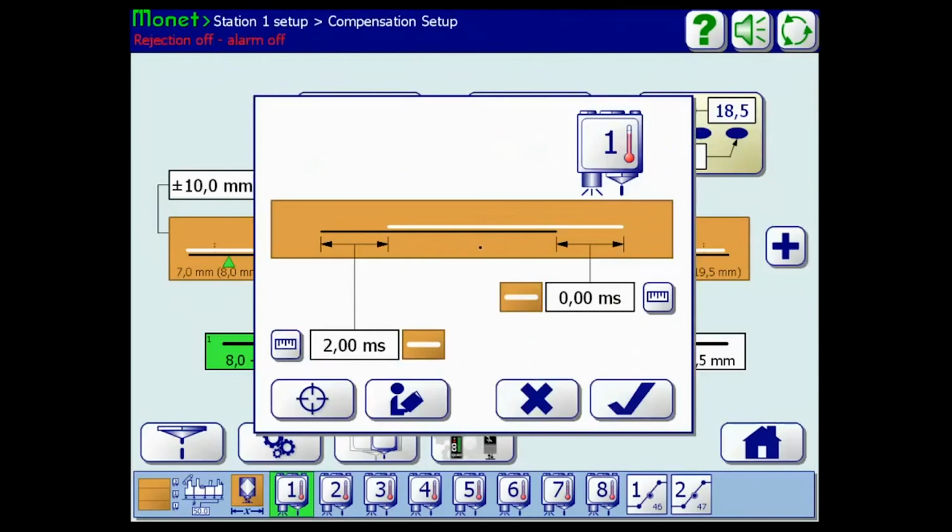There's on and off compensation for every glue applicator. This is just a generic image when you open up the menu. It's basically telling you that, in order for the glue to actually start where I programmed it to start, we have to compensate for the glue extruding from a nozzle and traveling through the air before it hits the substrate, that all takes real time. So what this is showing you in layman's terms is, we're firing the valve 2 milliseconds earlier than it would on its own to get our glue to start where we programmed it to start.